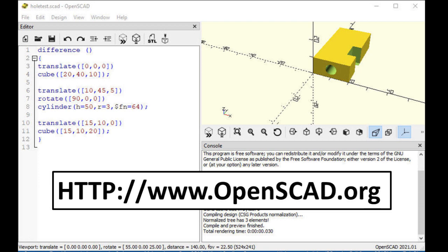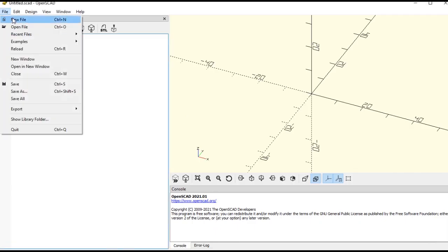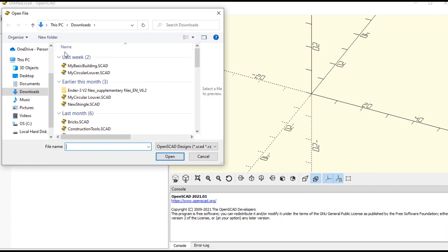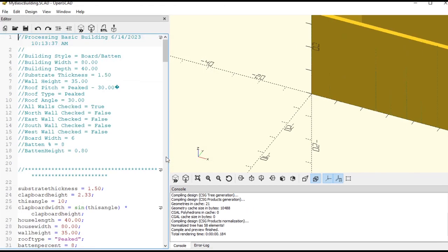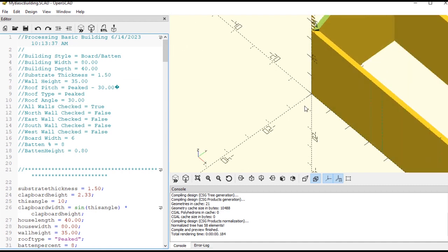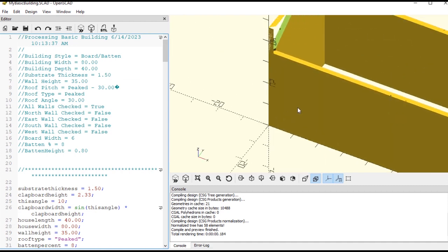Here we see the specification for cubes and cylinders, along with their positioning. Our generator allows us to create objects we want by filling out a form, kind of like ordering something from Amazon, and the generators translate our specific wants into tailored geometric specifications. When OpenSCAD is started, we click on File, Open File, to import the SCAD file the generator created. We see a rough depiction of the structure primitive we just created.